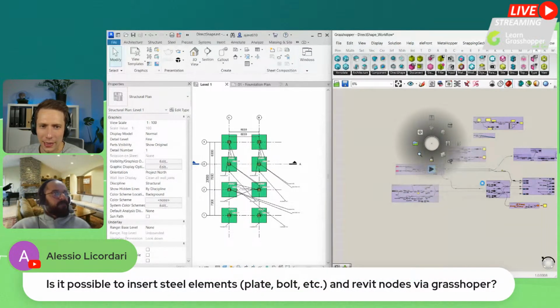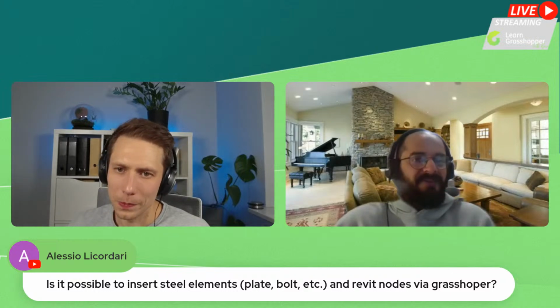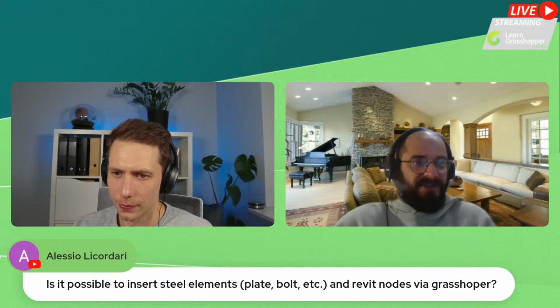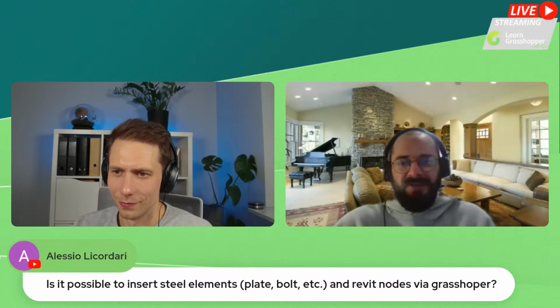Alessia asks, is it possible to insert steel elements, plate, bolts, and the Revit nodes through Grasshopper? There is no specialized component, but it boils down to the families, how you have defined your families. If you are using adopted families, yes, this can be done. If you are using some generic family, this can also be done. And then you have to select the locations. So if you have good families, then you can create really good elements in Revit, even using Rhino.inside.Revit.